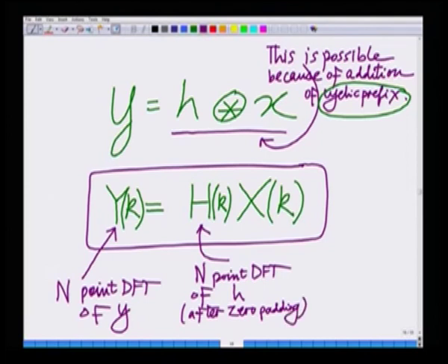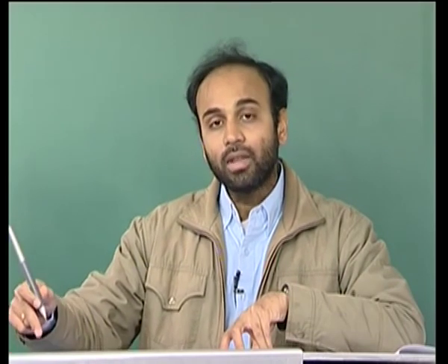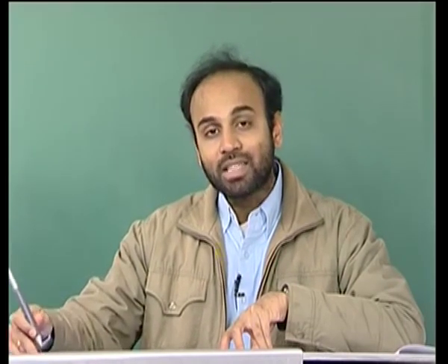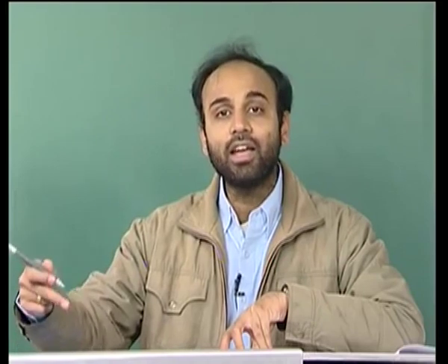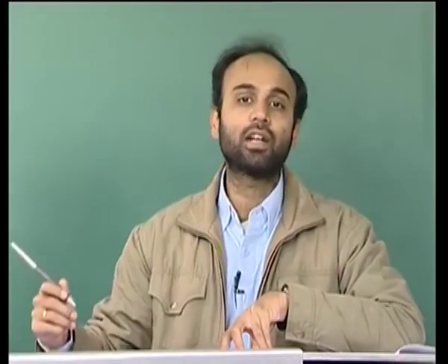And Xk is nothing but the DFT of the transmitted OFDM samples, but the transmitted OFDM samples are themselves the IFFT or the IDFT of the capital X's, x0, x1 up to xn minus 1. Hence, DFT of IFFT gives me the same original transmitted symbols.